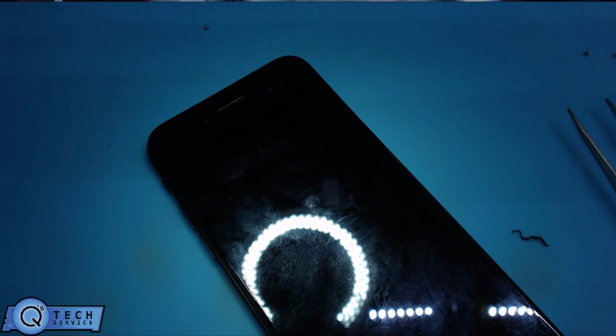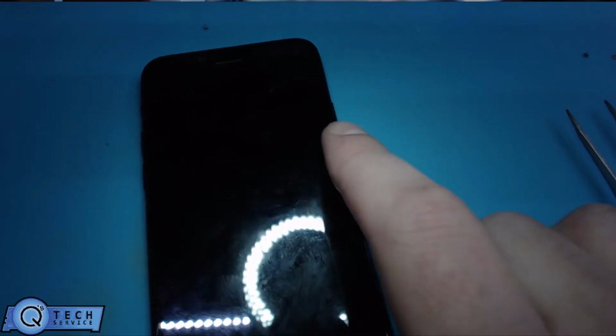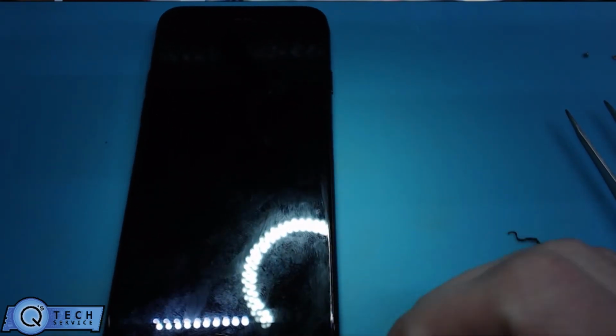And you can see in the middle of the video, when I removed it and was running the jumper wire, I just tapped the ball and it came free, and it was on the end of my tweezers. So we know this is a common issue. Apple should recall this. It's not fair to customers, but that's basically showing you how to repair the audio IC. It's a big problem. I fixed lots of them, and it should be addressed.